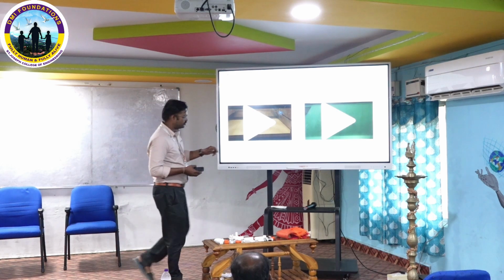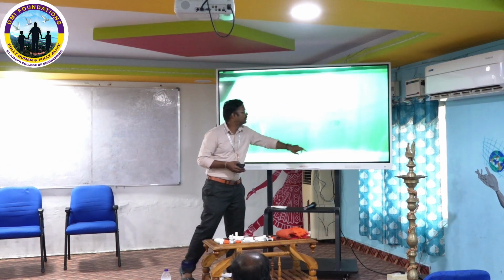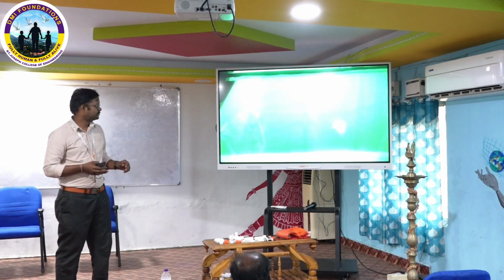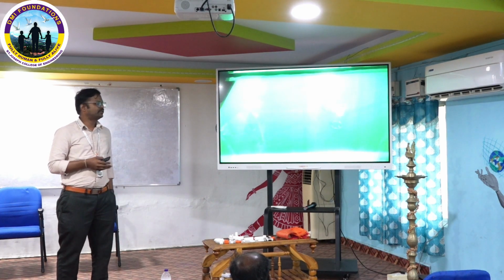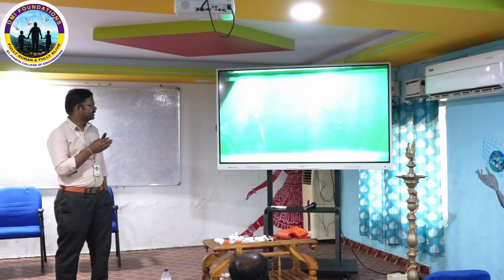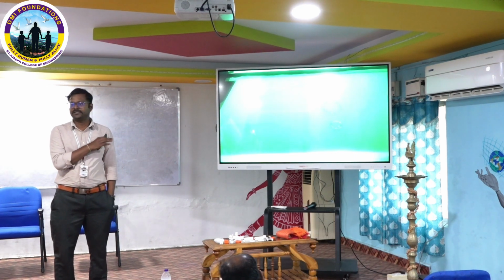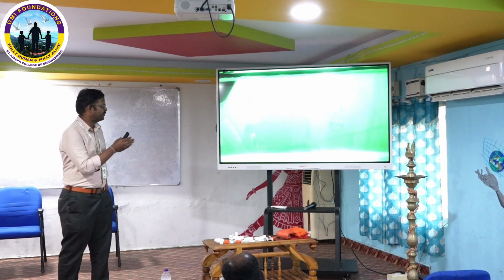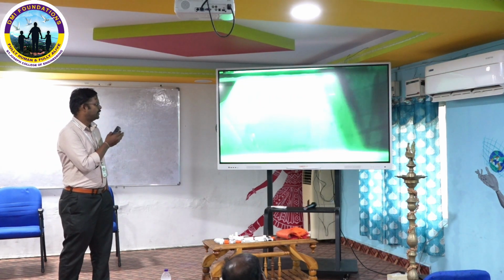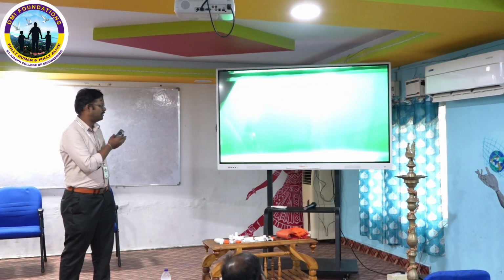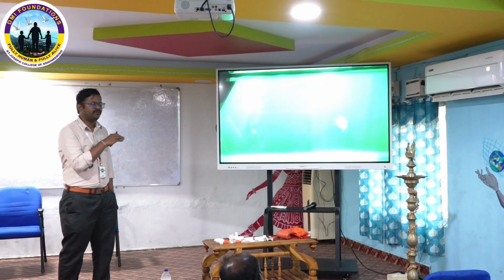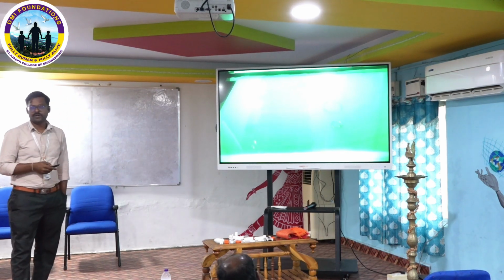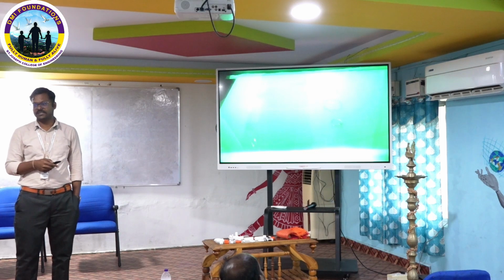Next video I am going to show you is about metal 3D printing. You can visibly see the melting of the powder. Here we are using a 400 watt laser. It is melting the powder. Sintering is nothing but partial melting. Here full melting happens. First of all, the first layer gets deposited on the build platform, then the layer gets melted with the help of the laser. This is the process flow for both powder bed fusion processes.